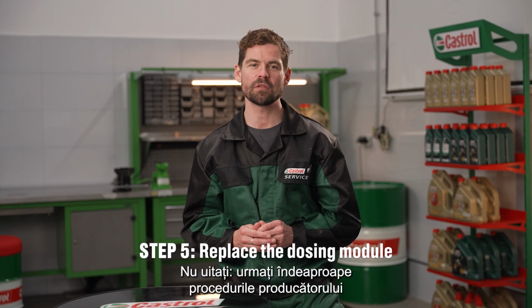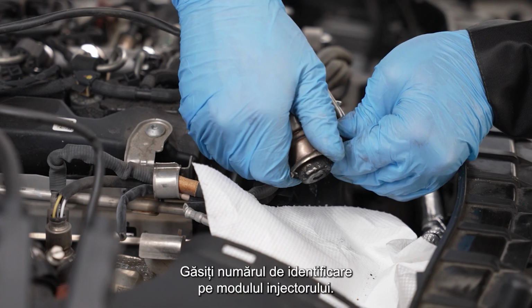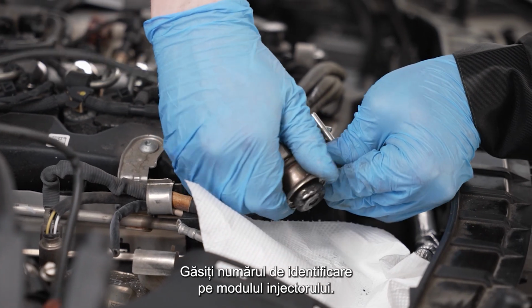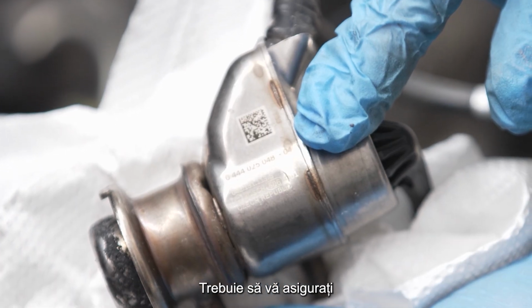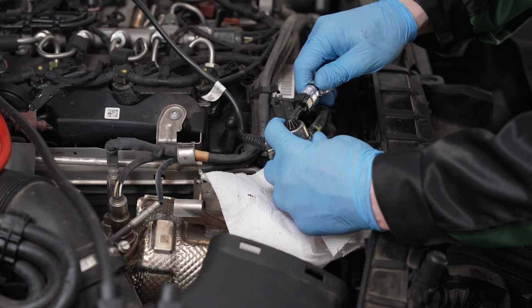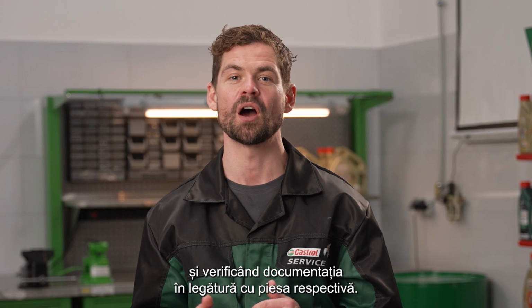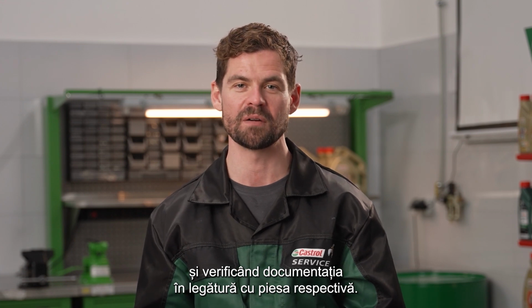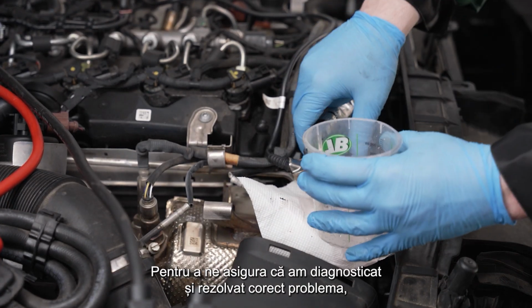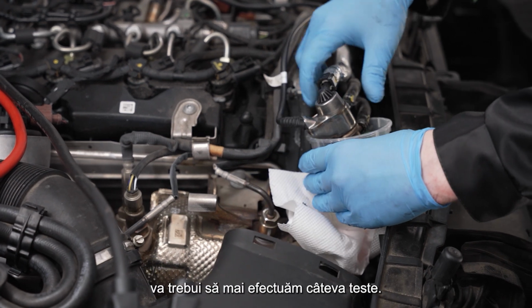Remember, follow the manufacturer's procedures closely and verify the part number of the component you're replacing. You can find the part number on the injector module. You also have to make sure that there haven't been any post-manufacturing changes. You can find out by logging in and checking the documentation around the dedicated part number. To make sure that we've correctly diagnosed and solved the problem, we'll have to run a few other tests.